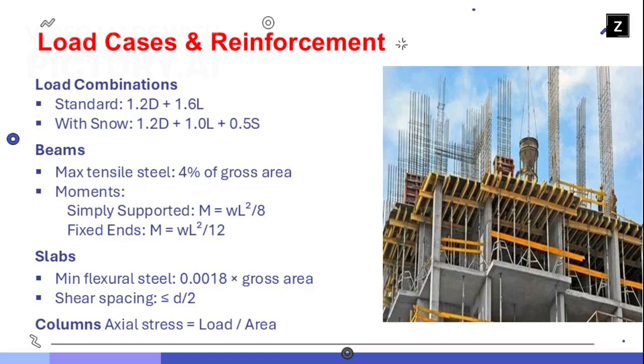Load cases and reinforcement are essential for structural design. The Dubai Municipality relies heavily on ACI 318-19 for load combinations. 1.2D plus 1.6L is the standard load case. Snow isn't common here, but in cold zones, it's 1.2D plus 1.0L plus 0.5S. Revised structural formulas: for simply supported beams, M equals WL squared over 8; for fixed end beams, M equals WL squared over 12. This helps evaluate maximum bending moments for design.